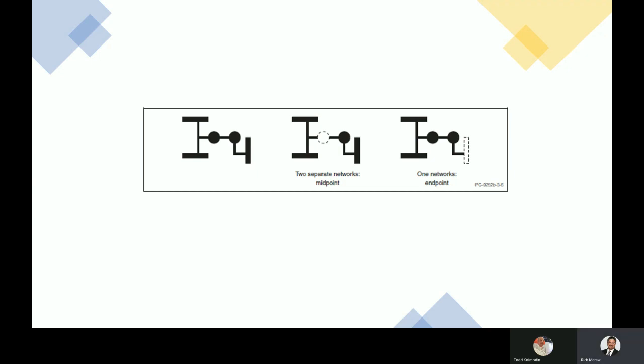Now that we know what a test point is, we talk a little bit about a net list. A net list is a connection of all the nets together. We have a series of traces running from one point to another point. Each set of points that are connected together is classified as one net. A PCB may have many nets across many different layers.